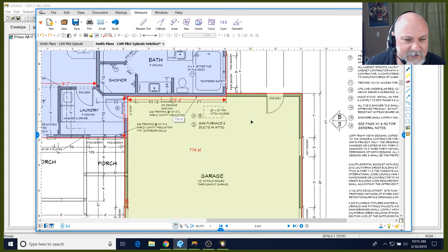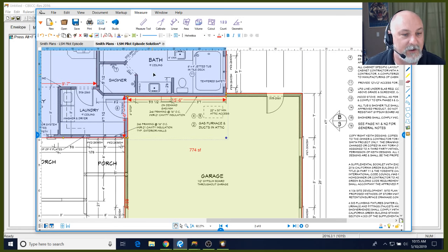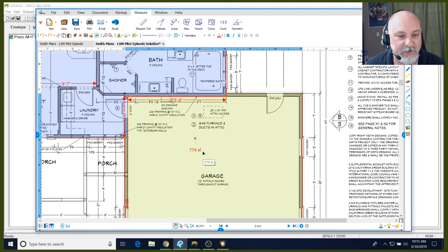So I went ahead and dimensioned these walls. I have 15.5 feet for that wall, 6.5 feet for that wall. That gives us 22 feet overall. A 9-foot plate, multiply that times 9, I should have 198 square feet. And that wall belongs to the conditioned area, and it will be adjacent to the garage area. That'll make sense when we start doing our inputs here.